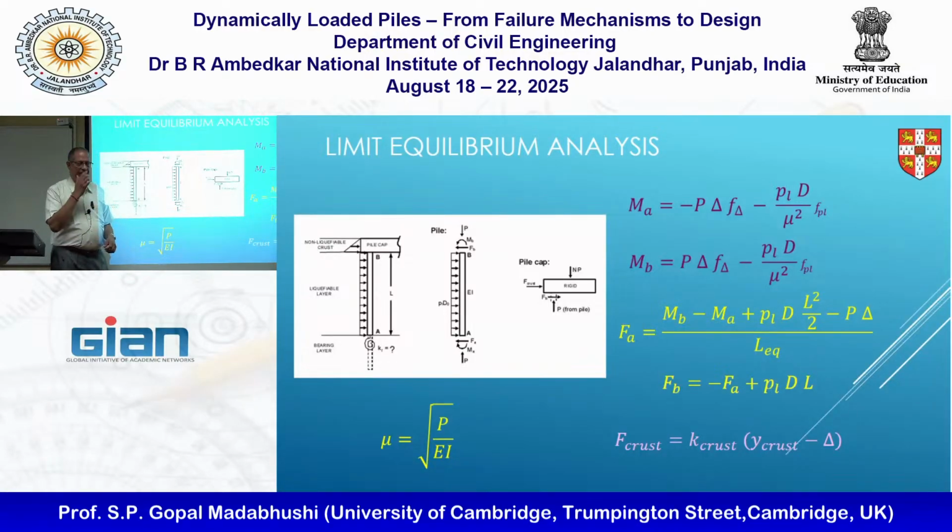One thing that we have added here, and this is the new bit, is the actual load the pile is carrying. We should not forget this, because these piles which are on slopes are not just there for fun. They are carrying some actual axial load. Why is this important? The moment this pile is going to try and bend outwards, I'm going to get that P times delta as an extra moment. So every element on this pile has to work to resist that P delta effect. Okay? So this is the equilibrium of forces.